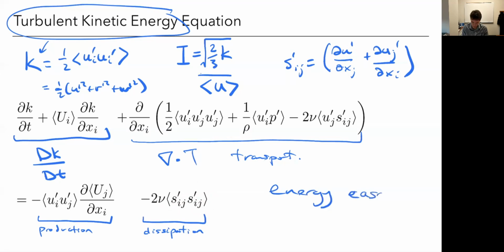You could think of it as a mechanism where turbulence pulls energy out of the large scale structures, transports it down to smaller structures, and then dissipates that energy at the smallest scales. And those small scales are determined by when this becomes significant. So that'll depend on your Reynolds number, where this viscosity and these velocity gradients play a role. At the point where that starts becoming significant, that defines those small scales that we have to resolve in our simulations.